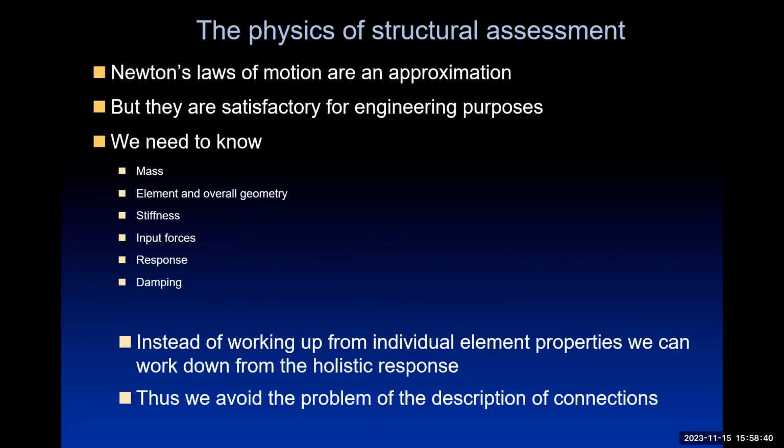And all we need to know is the mass which is involved, the element and overall geometry, their stiffnesses, the input forces, the response, and damping. Damping is the most difficult one to assess. In fact, what damping is the dissipation of energy.